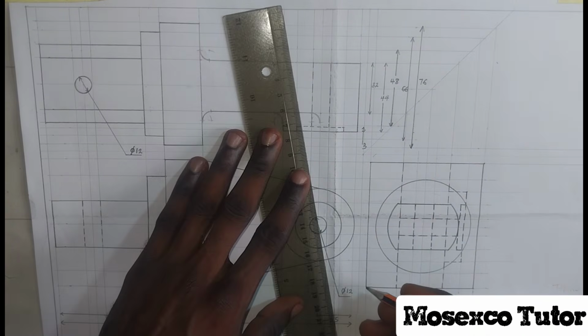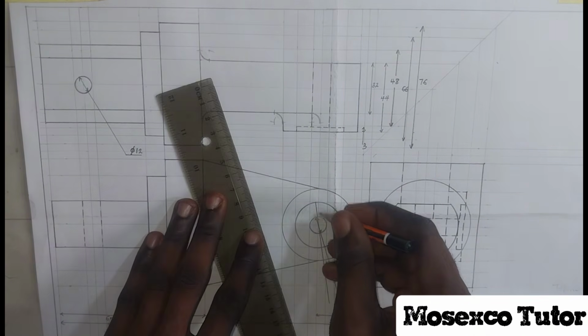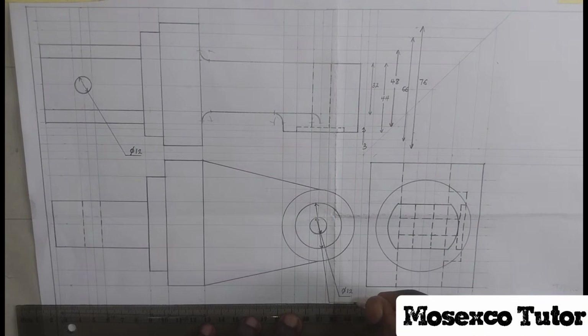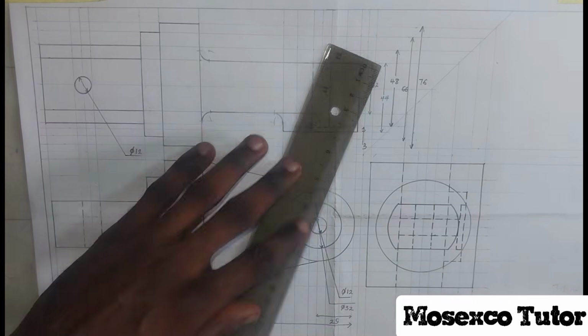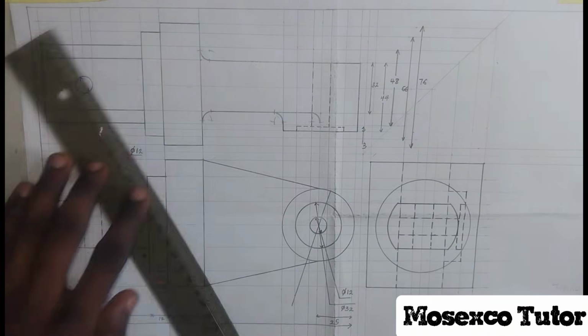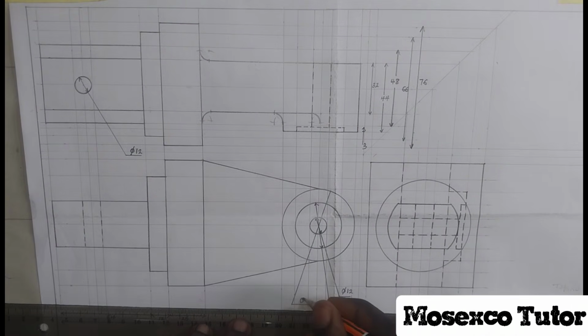But for third angle, you leave it to the side that you view it from. For third angle, if you view it from your left, it will be at your left. If you view it from your right, it will be at your right, unless otherwise stated. So in this question, we are asked to place it to our right hand side. So we put the dimensions one after the other.